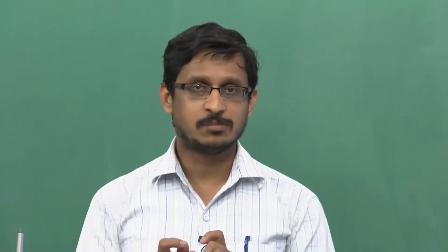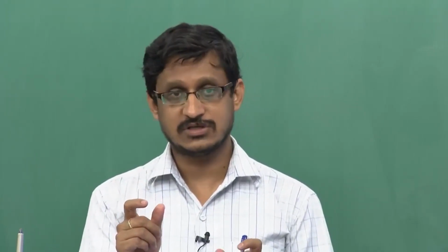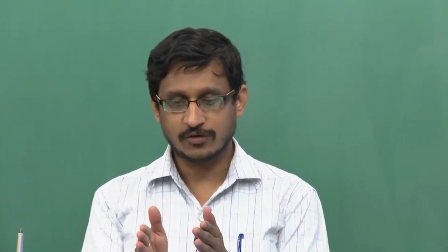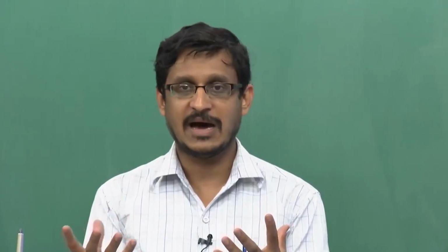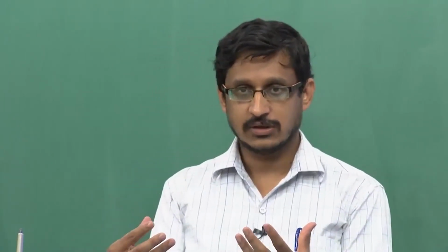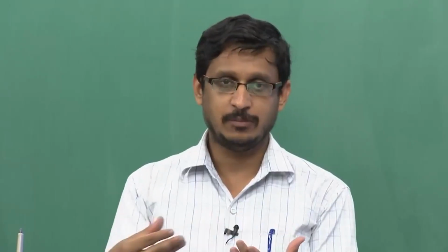A simple diode such as a PN junction, when you reverse bias it, you know from your electronics courses that there will be a depletion layer formed between the P and the N type junctions, and the width of this depletion layer is controlled by the reverse bias that you apply. The depletion layer mainly consists of immobile ions, which causes an electric field between them.